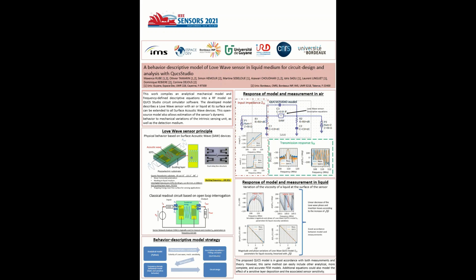But first, let's talk about the real Love wave sensor. Love waves are surface acoustic waves, which means that they propagate exclusively at the surface of a material. In our case, our device is composed of three parts: a piezoelectric crystal of ST quartz, a thin layer of silica which guides the acoustic wave, and two interdigitated transducers.